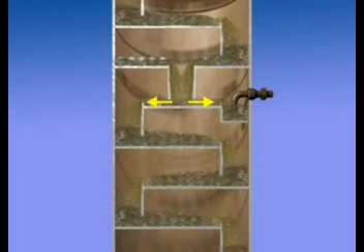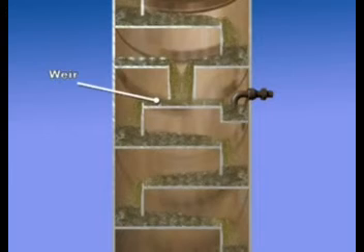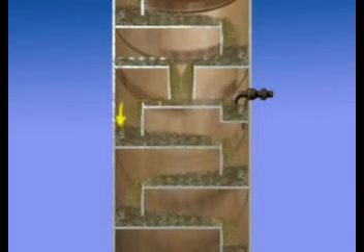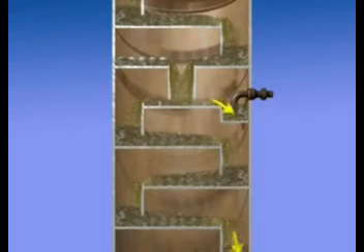On both sides of the downcomers on the tray below, a weir is present to maintain the appropriate liquid level. The left side of this tray continues the liquid downflow. On the right-hand side, the tray level drops to create a larger hold-up area from which the liquid can be pumped out to the appropriate equipment.